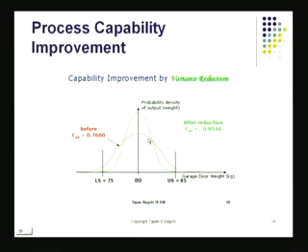But if I make the process tighter, that means if I reduce sigma, I can go from that green line to this red line, which also is not quite perfect yet because it has still got a little bit of tail there. But certainly CPK has improved from 0.766 to 0.9544. This is the better process, clearly. It will have very few rejects.